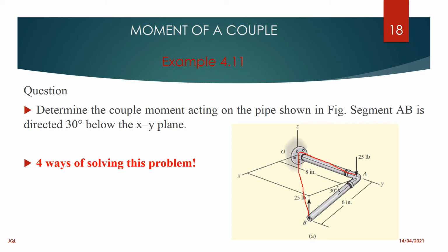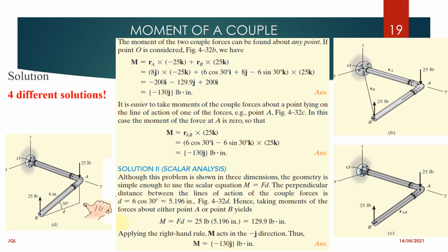Try to solve this problem using different ways. That is going to help you understand the whole concept of a couple, a moment, and how to calculate the moments. Here, the first solution is of course using the vector analysis, and the second one is by using the scalar analysis.